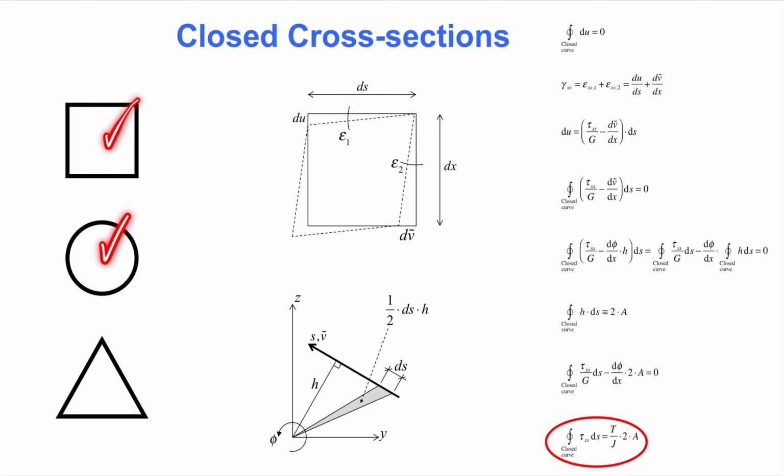On the next slide, we start the examination of closed cross-sections. Closed cross-sections have one or more cells and carry torque far better than open cross-sections. If one draws a continuous line around the circumference of the cross-section, then there will be more than one line. For this square cross-section, one line follows the outer edge and one follows the inner edge by outlining the cell.